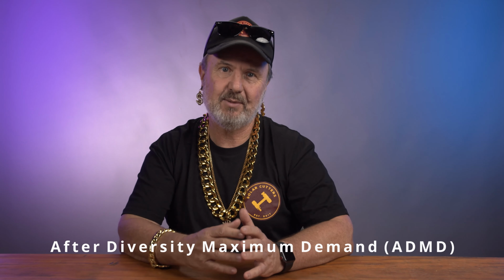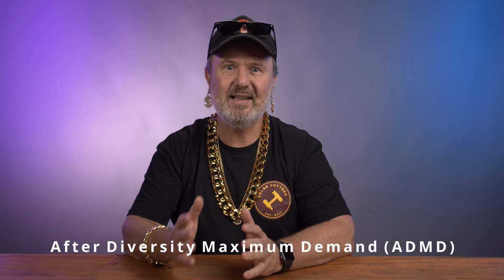Here we go. So today, pretty short one. Really, I'm going to focus on what's known as maximum demand calculations. Now, maximum demand calculations are something that you might be familiar with for on-grid installations, where you've got a certain capacity from the grid. You have to consider the number of socket outlets and light fittings and dedicated appliances, etc., and work out what the maximum demand after diversity, MAD, maximum demand, MDAD, maximum demand after diversity.